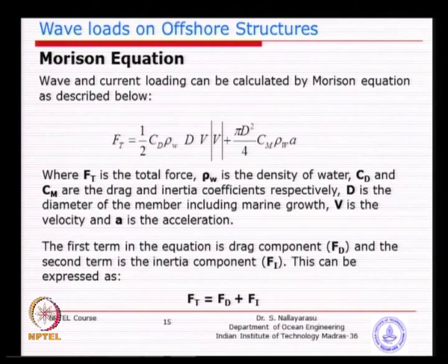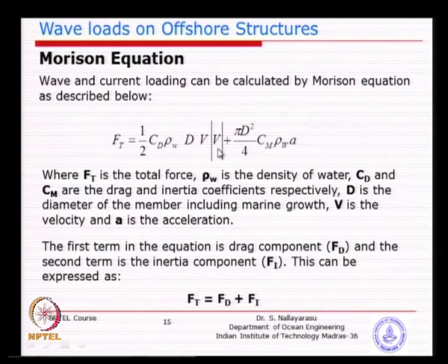So, you could calculate the fluid velocity and fluid acceleration, and then substitute here. If you go back to those 4 formulas we had, VH, VV, AH and AV, you could calculate those and substitute here and try to find out the force on the structure, but unfortunately that formula, if you look at it, is varying with space and varying with time. So, that means it is not one value you are going to get, you are going to get several values. So, we need to find a methodology for which value to be used for design,